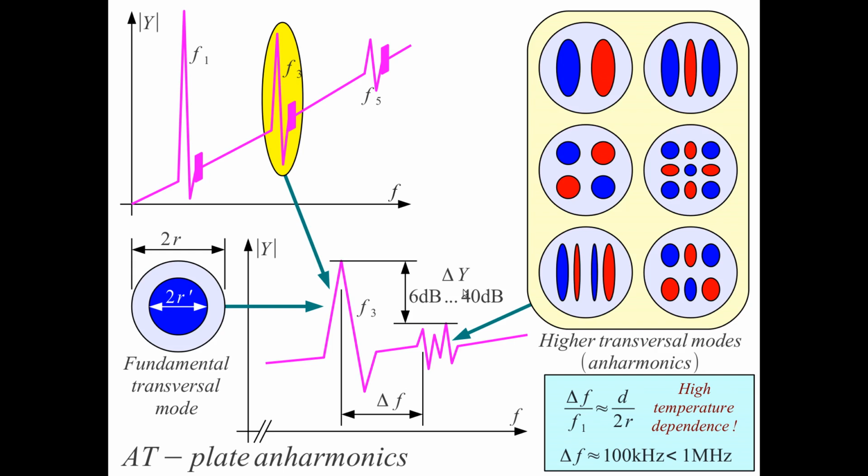A crystal designed for crystal filters will achieve 40 dB of suppression of unwanted modes, at the cost that this only happens at one particular overtone frequency, at one particular thickness of the crystal. So this is very dependent on the crystal design. Each fundamental thickness resonance, the fundamental, the third overtone, the fifth overtone, has these spurious transversal resonances that will cause us problems, especially in filters.